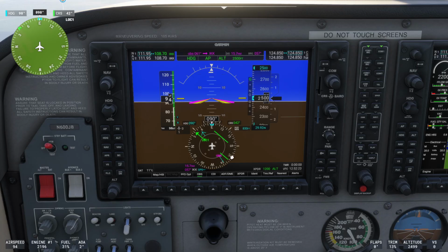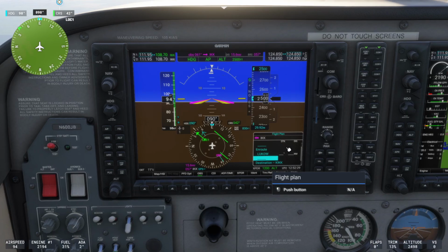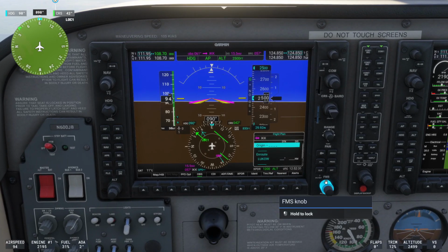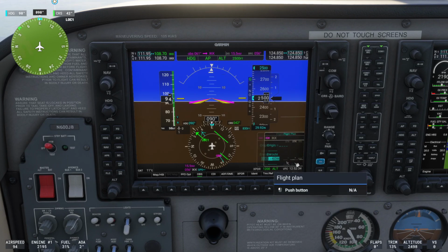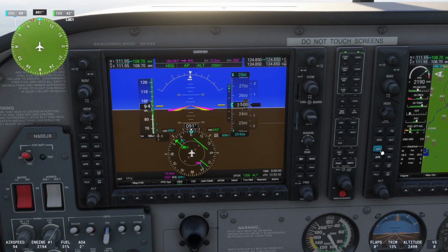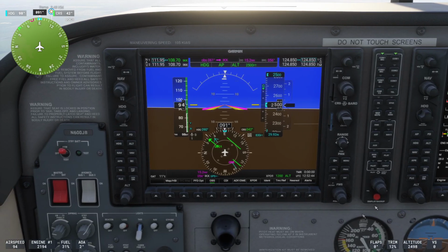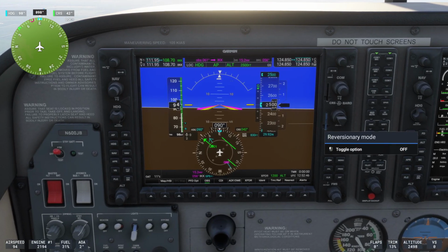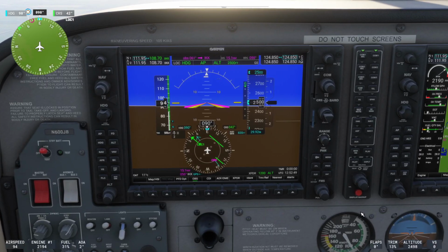We're allowed to tune in specific courses to and from specific GPS waypoints, in this case our DME station. But what it also does, and what's important for this, is that it prevents sequencing this flight plan. So instead of going to the locator and then going to IKK as we pass over those GPS waypoints, it'll hold those in the GPS as the active waypoint until we put in a next direct course and we say, okay, no more OBS mode.